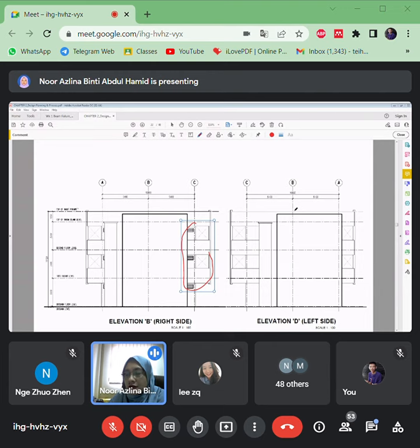So these are very important details for us to design as well. Sometimes we cannot see the structure clearly from the top view, so we have to check the other sides. We need to confirm the thickness, because from the top view we cannot see the thickness. To calculate how much concrete is needed per area, we have to check the other elevations to analyze the sizes, especially the height.